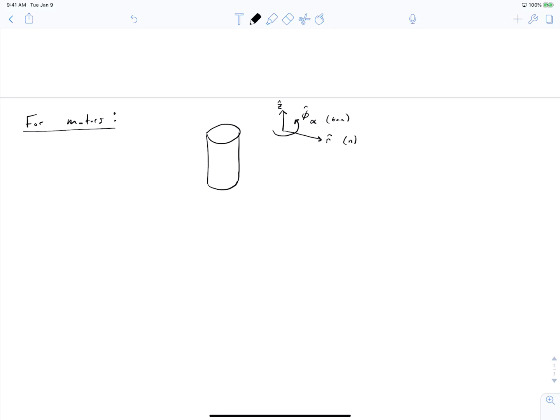And sometimes we'll be considering this in Cartesian coordinates because we'll unroll our motor. We'll take the rotary motor and we'll unroll it to be a linear machine to make drawings easier, to make math a little easier, to illustrate points. But in this case, let's talk about it being a cylinder. And we are primarily interested in forces that are acting on the radial surface of the cylinder. So we want to know what forces are acting on this radial surface, and we're going to assume that our fields are only in the radial or normal and tangential direction, that we've got no axial component. That's the 2D assumptions we've been talking about.